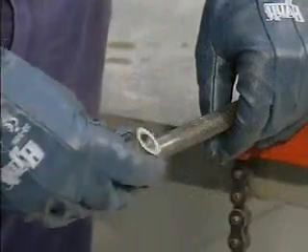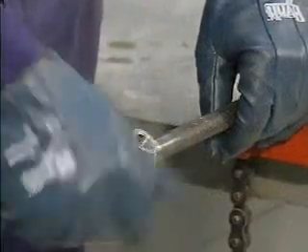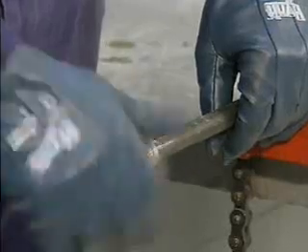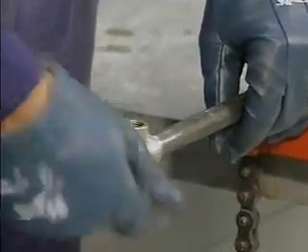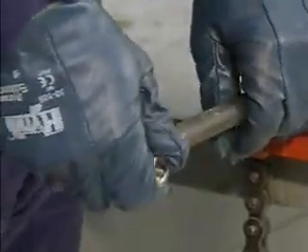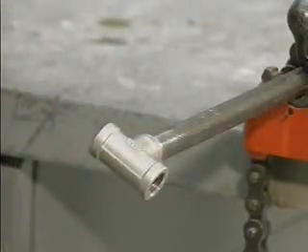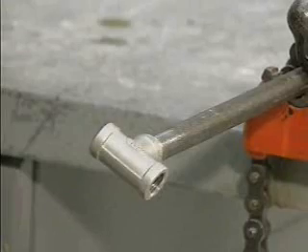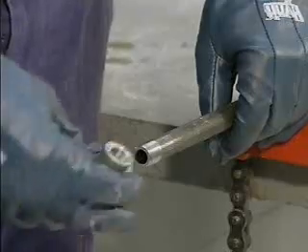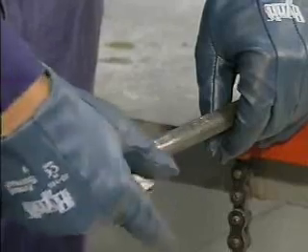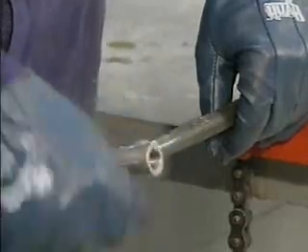Threaded joints or screwed joints are made by screwing the outside threaded end of a pipe into the inside threaded end of a pipe fitting. Threaded joints have a specified engagement depth. The engagement depth is the distance that the pipe must be turned into the fitting. The engagement depth requirement must be reached for the joint to be properly threaded. As pipe size increases, engagement depth also increases.